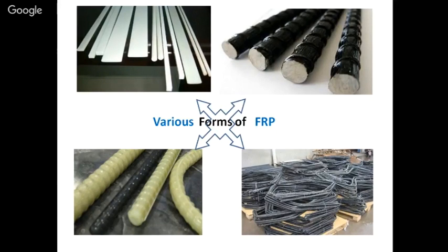So now, after detailed research across the world, now the GFRP rods are available, epoxy-based rods are available, carbon-based rods are available in required form, which means it is not only available in plain form, it is available in ribbed form also. So these are FRP bars having good elastic modulus and tensile properties, but you can't bend and deform the entire FRP into stirrups. So our factories have already made stirrups in the desired form. The last image stands for FRP stirrups. It is available ready-made. You can go and buy and use in our RCC structure instead of stirrups.